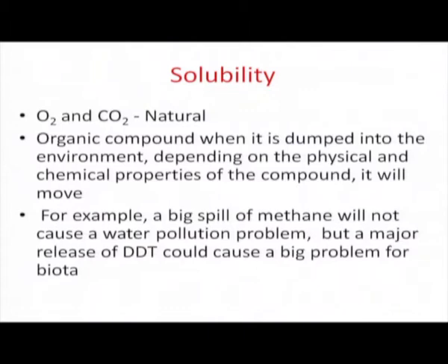Already we discussed the solubility of chemical substances in water, and we discussed elaborately the solubility of oxygen and carbon dioxide in natural water, and both are soluble. For a healthy aquatic environment, we discussed that a minimum of 4 milligram per liter of dissolved oxygen is enough. Similarly, carbon dioxide solubility in water acts as one of the natural buffers in the aquatic system. So, these species are important, as we already discussed.